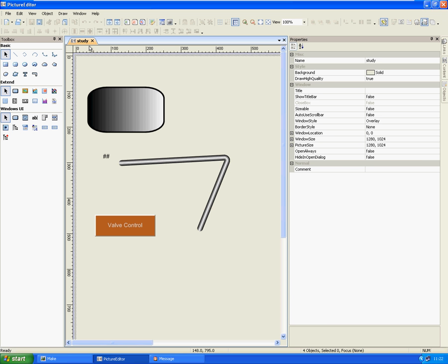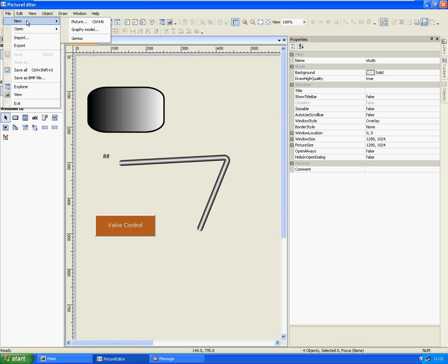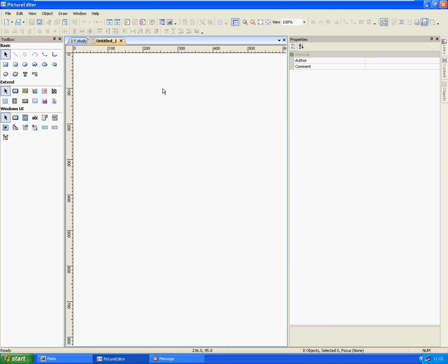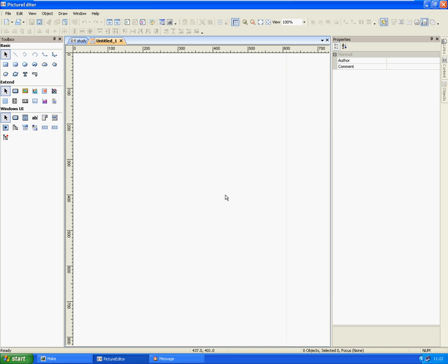Learn about the Genius Development Interface. Open the File menu in the Picture Editor and choose New Genius. The Genius Development Interface pops up. It is similar to the Picture Development Interface. Both of them are composed of a menu bar, toolbox, picture editor area, and property window, and the operation is basically the same.